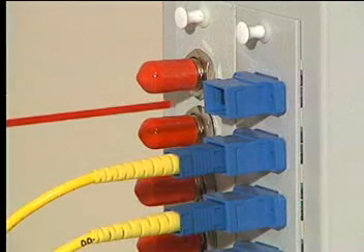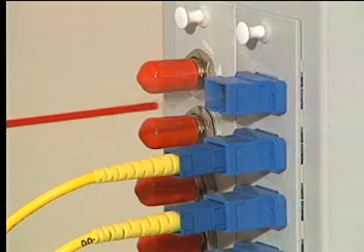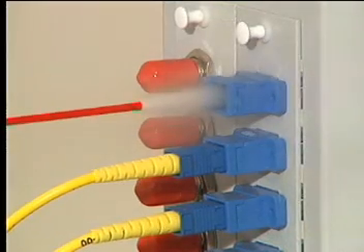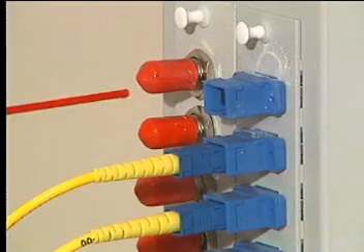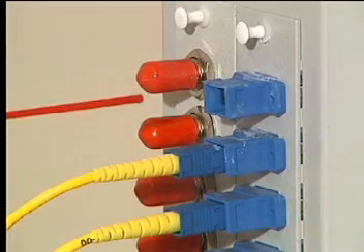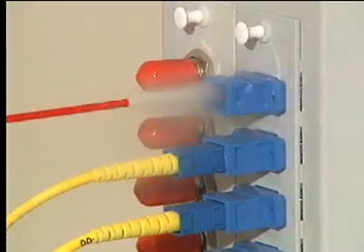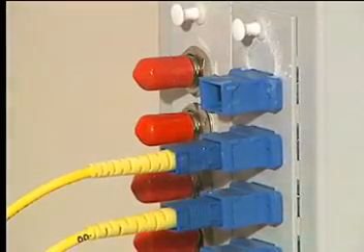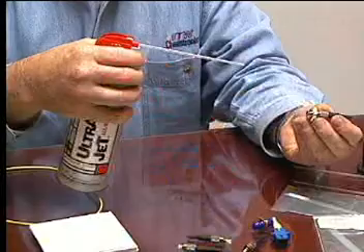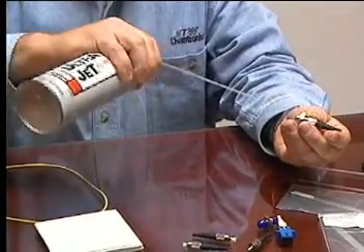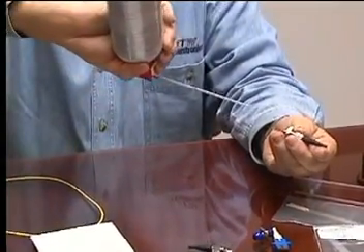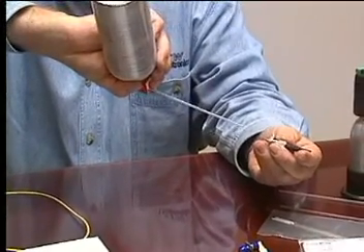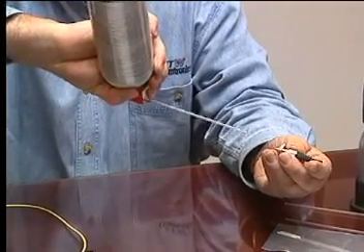The extremely cold liquid will be forced into the connector, instantly freezing the fiber end face inside. Such a rapid temperature drop could easily cause the glass end face to crack, ruining the connector. Even if the connector is not damaged, the liquid will leave a contaminating residue. Some dusters are designed for use in more horizontal positions, but if completely inverted, may still eject liquid propellant mist.